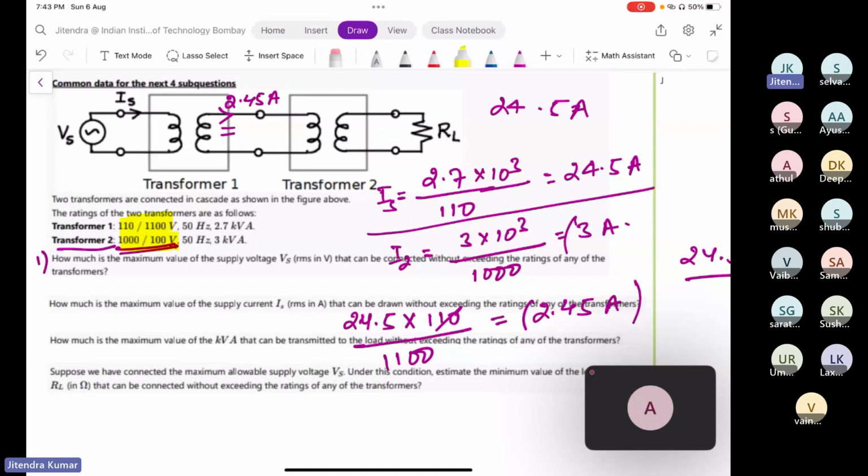There will be many cases where you can apply voltage less than the rated voltage. Did you get this statement? Yes. So in that case, if you apply less than the rated voltage, you are bound to get the higher value of current. Yes, exactly, lower voltage side, higher current to maintain the kVA. So when you are trying to find out the current, you must ensure that you have applied the rated voltage.